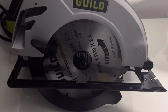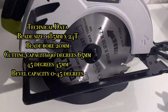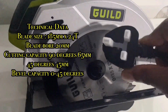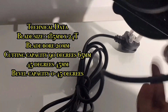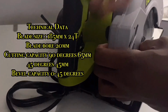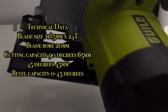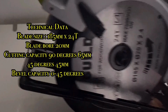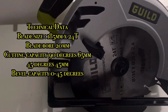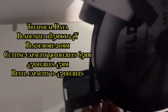For the Gullet power tool, we've got a blade size of 185mm, a blade bore at 20mm. It's got a cutting capacity of 90 degrees at 65mm and 45 degrees at 45mm. So it essentially means it can cut at various angles up to a depth of 65mm or 45mm, depending on the angle. And also a bevel capacity that's capable of doing cuts from anywhere between 0 to 45 degrees.